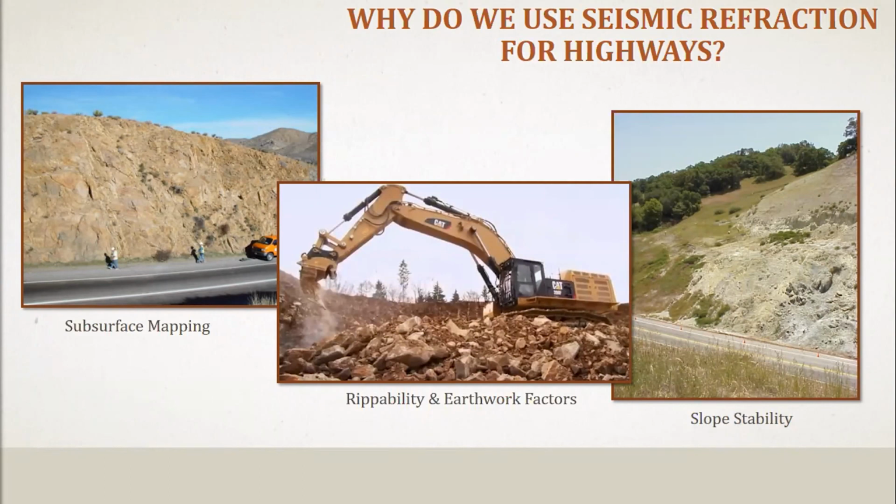Since transportation projects can involve large amounts of earth movement, we also provide rippability estimates. These estimates are based on the seismic velocity of the material, which is closely related to the density of the material and gives construction a guide on what equipment is appropriate and if blasting is required. We can also provide earthwork factors of known materials, which is basically how much the volume of material can change after excavation from shrinking or swelling. Material excavated on site can then be properly accounted for when filling and leveling for other areas or sections on site or at other projects.